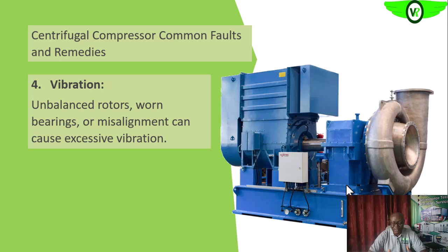So what are the common things that can cause vibration? Unbalance of the rotor, okay, can cause vibration. In this case now, unbalance of the impeller, the compressor impeller, can also cause these unbalanced forces that will increase the vibration.